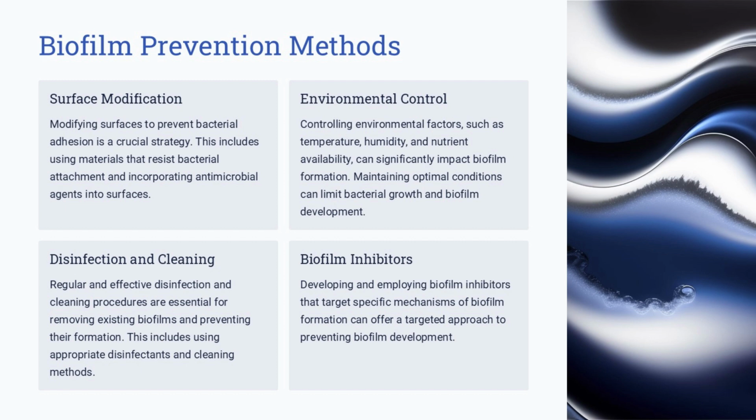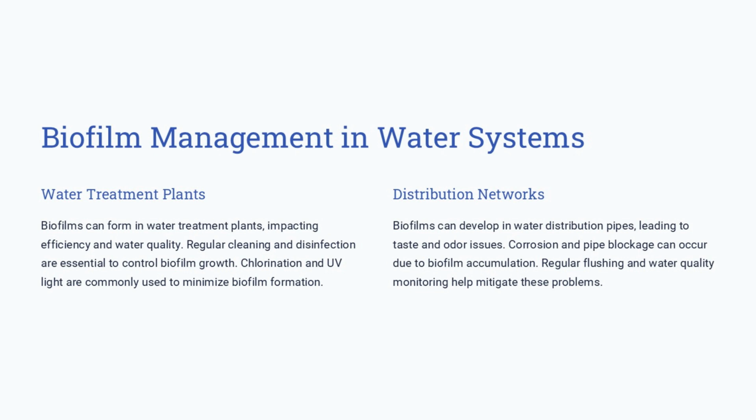Regular and effective disinfection and cleaning procedures are essential for removing existing biofilms and preventing their formation. Using appropriate disinfectants and cleaning methods is crucial. Developing and employing biofilm inhibitors that target specific mechanisms of biofilm formation can offer a targeted approach to preventing biofilm development. Biofilms can be a significant issue in water treatment plants, impacting efficiency and water quality.